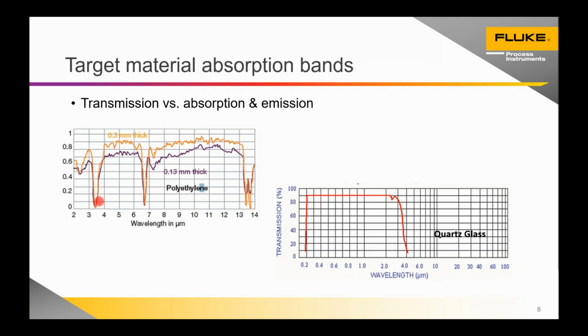So we make specific sensors for plastics with what we call a notch filter, so very specific to the application. Glass is also interesting in that sometimes we need to measure glass. So where the transmission is lowest, here we can measure glass in process.